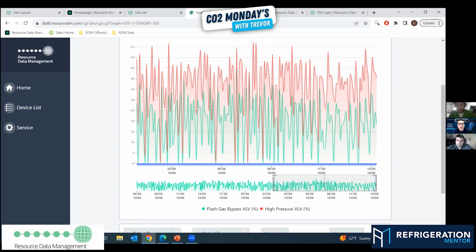So anyways. Yeah, no, because the valve is going from 55% down to 0. What would you say, like 10%? What are you looking for? 5% would be super tight. Yeah, I mean, to be honest with you, Trevor, controls is still going to have a lag in it. You're not going to get it perfectly streamlined, but I don't want to see 25 to 35%, way up there, way down, way up. I want to see 10%, 15.